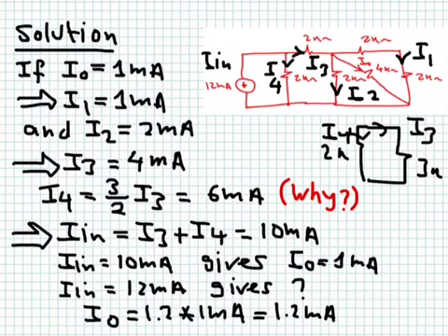Okay? Because it's a linear relationship, it's a linear system. So 1 milliampere at the output corresponds to 10 milliampere at the input. So what corresponds to 12 milliampere at the input? What is the corresponding output? Well, you apply linearity. If this was 10 milliampere, I got 1 milliampere. If you make this one 12 milliampere, this means use the scale factor of 1.2. Then the output will also be scaled by 1.2. So multiply 1 milliampere by 1.2, you get 1.2 milliampere.